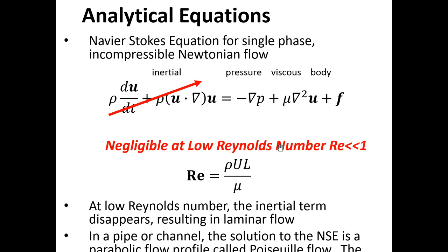All right. The Reynolds number is a dimensionless number, and mechanical engineers, thermal engineers, and fluids engineers use dimensionless numbers a lot. Dimensionless numbers generally describe the relative effect of one phenomenon versus another. So if this fraction is less than 1, that means the inertial forces are less than the viscous forces. In the Navier-Stokes equation, that means these terms become insignificant compared to these terms.